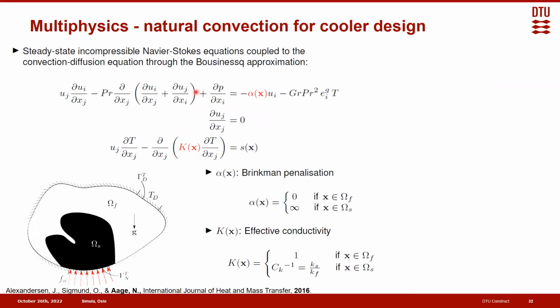So what we have here is the Navier-Stokes system for low Reynolds numbers, with low turbulence modeling. We have a temperature coupling, so we have this transport equation, and we let it couple back through the Boussinesq approximation. So we have natural convection. Okay, so what can you do with that? Well, again, you formulate the problem. You have to do some interpolation functions, as you cannot see here, but they are there.